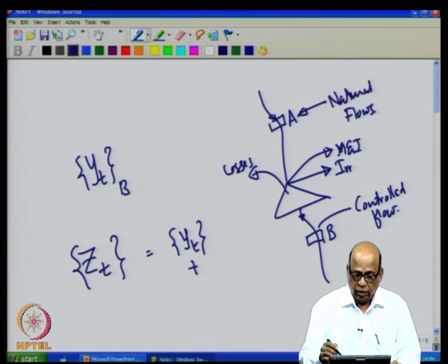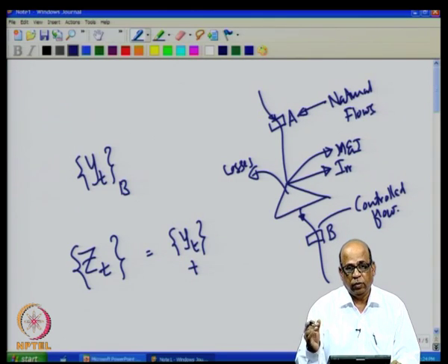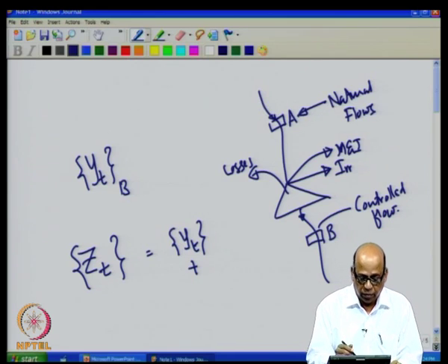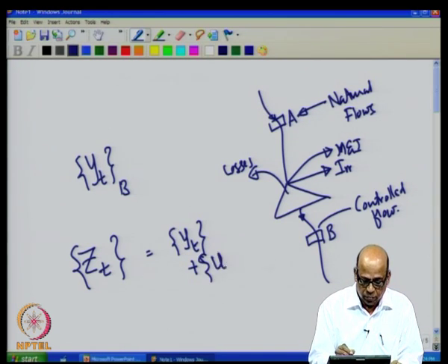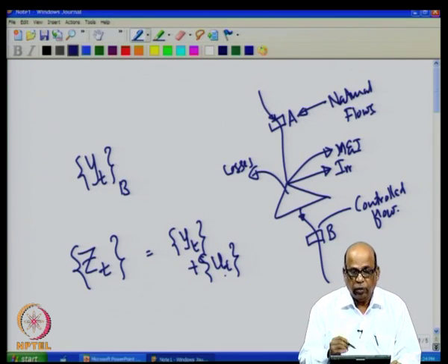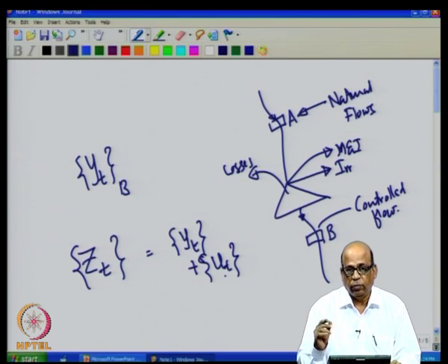So, 1 to 50 every year, how much of water that has been actually utilized, these are called as the upstream utilizations. So, you add all the utilizations, I will call that as UT, which is upstream utilization. So, what we have done now is whatever that is observed here plus upstream utilization. This also includes losses. Remember, when I write UT, it is utilization plus losses.